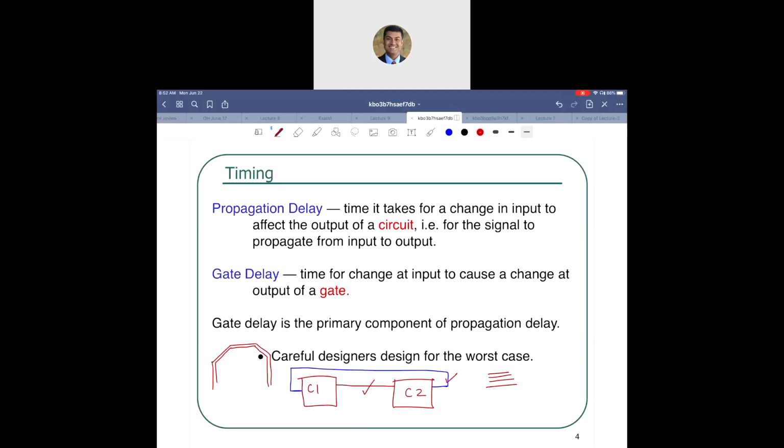So you will see those squiggly traces there. And one of the main goals is to have all their lengths equal. So it's more of an art form than an engineering issue, but it's almost art the way they do it. All right. So I hope that discussion was helpful, and all of this is to tackle one villain, right? The villain being the gate delay.